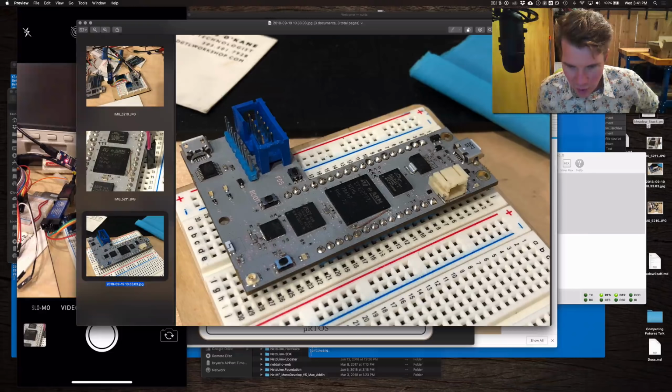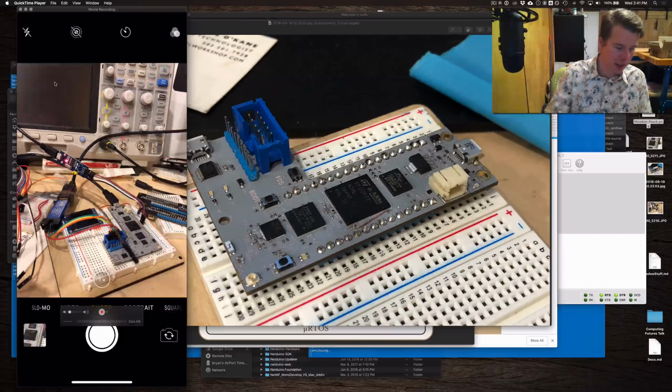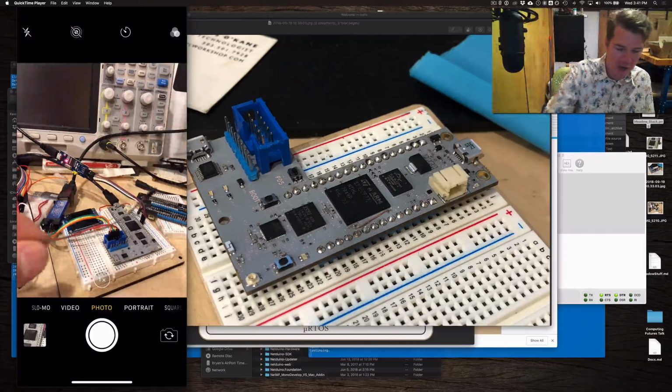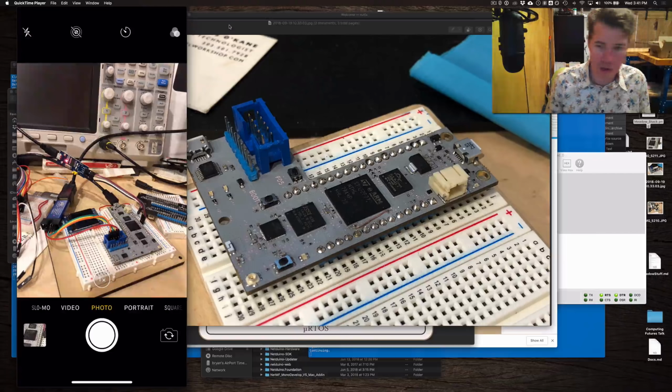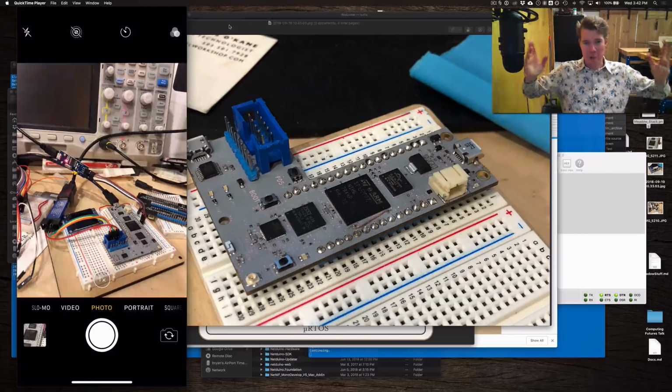there's an LED, I think this is the LED, and this is a capacitor, and so you can't tell, but this is hair-thin wire. This is some really thin jumper wire, something like this. I opened this up, and there was a braided wire in there, and I took one little piece of wire and had to solder that under the microscope, and lo and behold, we did that, and then I plugged the board in, and the board showed up in DFU mode, the board showed up in non-DFU mode, and we saved our prototype.